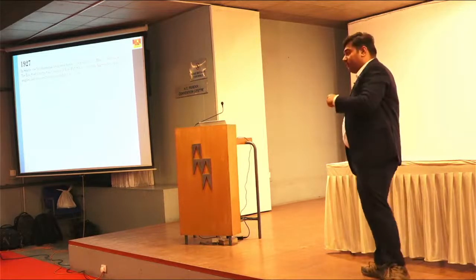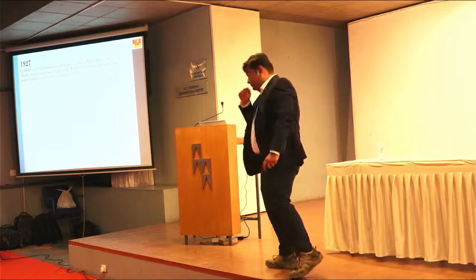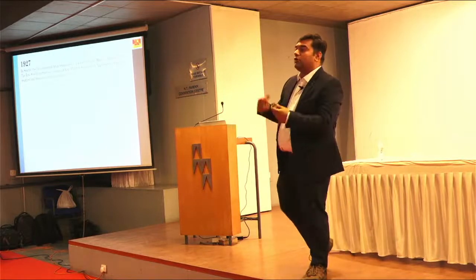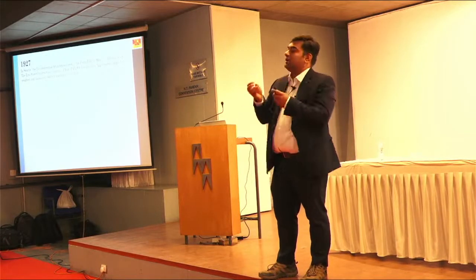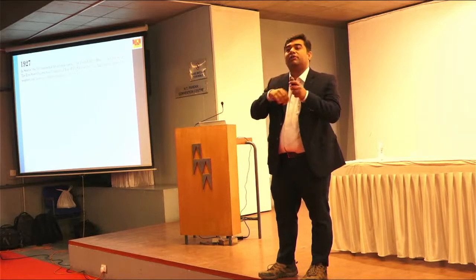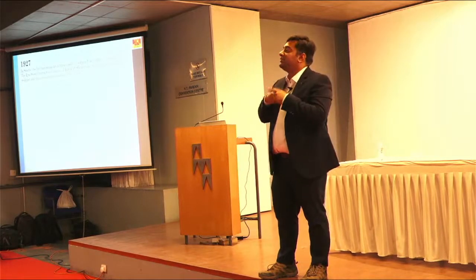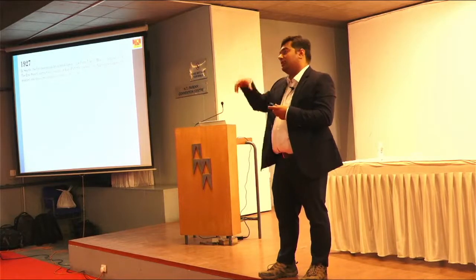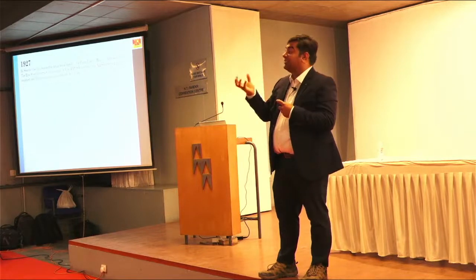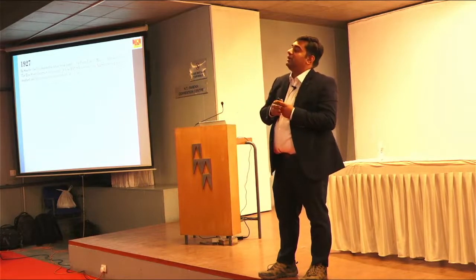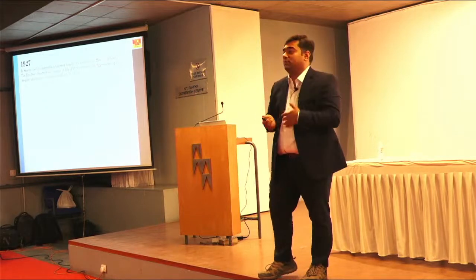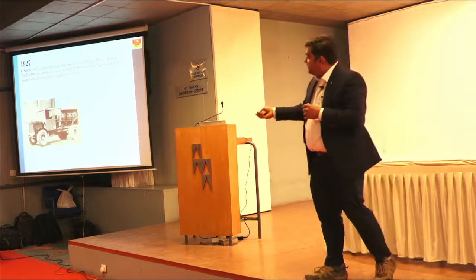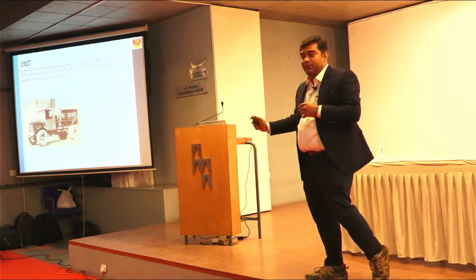So at that time there were two types of concrete mixers. There was one mixer which was a dry concrete mixer and the other was a wet concrete mixer. Dry concrete mixers are mixers where dry material is put in the transit mixer along with water and the transit mixer mixes the mix. Whereas the wet ones are the ones where there is a central mixer in which all the materials are put and they are mixed in the plant itself. The transit mixer only transports them from one place to the other place. So in 1927 they could do it. This was sort of a first transit mixer, a horizontal type.